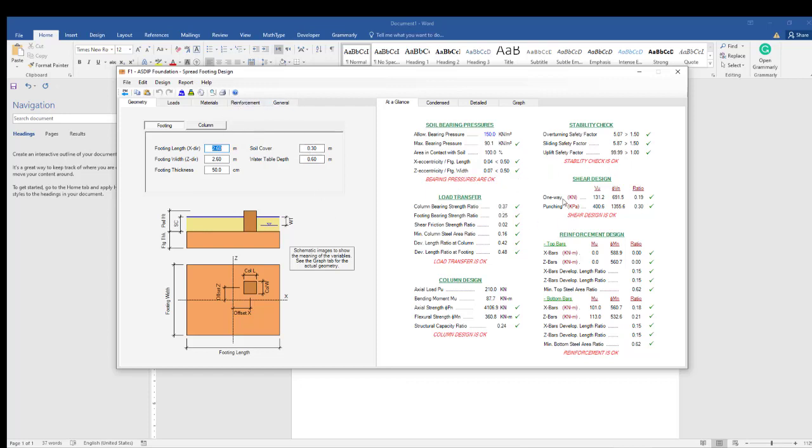So now we can see another thing: the shear design ratio is 0.9, which is okay, and the punching is also okay. The reinforcement ratio is very low, which means we have a lot of provided moment capacity, giving top and bottom rebars in the z direction, and all these parameters are quite good. The column is also okay. We have 150 and 200, which is quite higher, and the actual strength is very high.